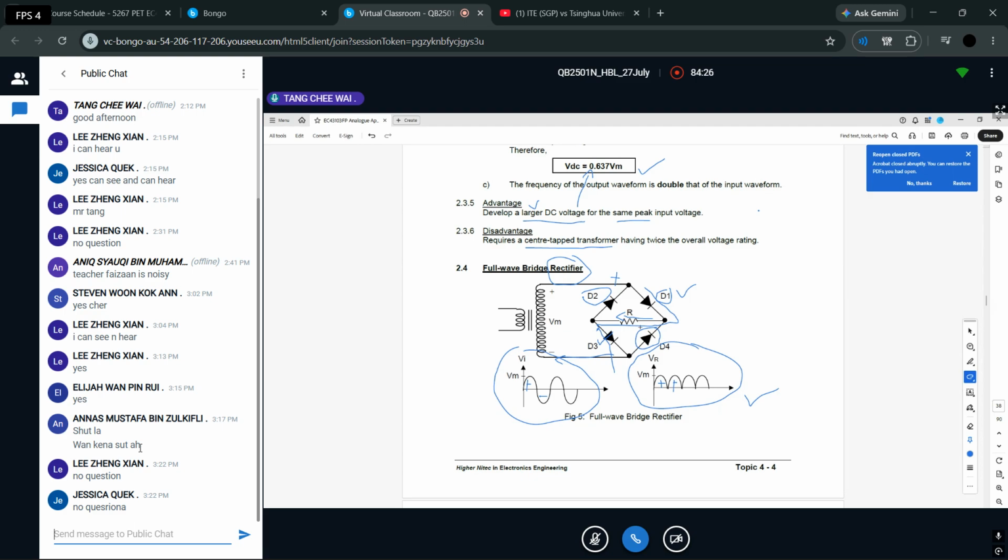As I mentioned, I repeat, we are only doing rectification now. We haven't come to filtering yet. So this is the waveform you will get after the rectifier. And it's full wave. Why do we call it full wave? Because we rectify both the positive and the negative half to get both positive halves here. For one cycle of the AC, we get this one as in DC. That's why you can see VM here. Basically, we are actually in DC. That is the conversion from AC to DC. That is the purpose of your rectifier.